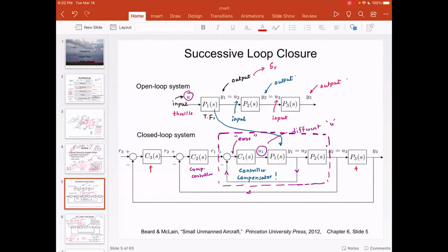Now, the idea is once we have the transfer function, once we implement a feedback loop, once we add a PID, at the end of the day we try to move poles to the left-hand side of the plane so that the system is asymptotically stable. That's all we are going to do, but we are going to do that process in a step-by-step fashion. We will look at the innermost loop, then go a step further, and successively we will completely control the open loop system.